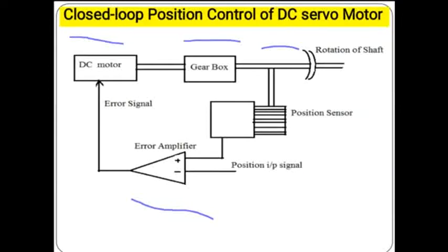The working of this block diagram is the same as before, and it can be applied as a servo mechanism. First, the DC motor is connected to the gearbox, and the DC motor is controlled by the feedback element, which is a potentiometer. That means if the resistance of the potentiometer is changed, the voltage drop also changes. According to that, the DC motor changes its signal and we get different positions. So the explanation is the same as before.